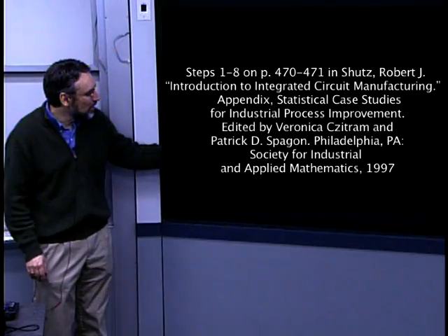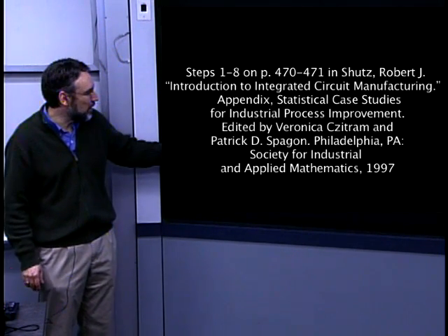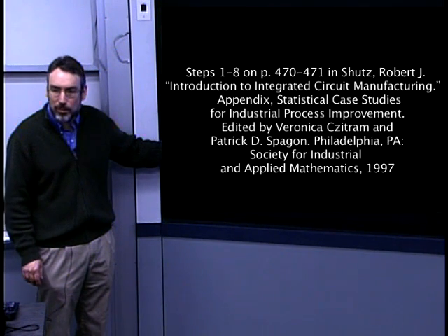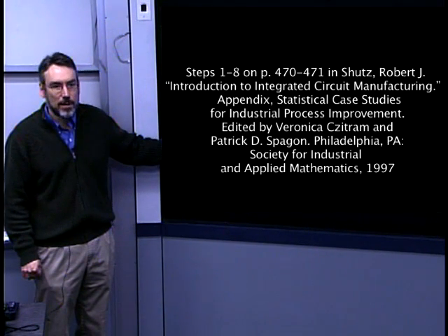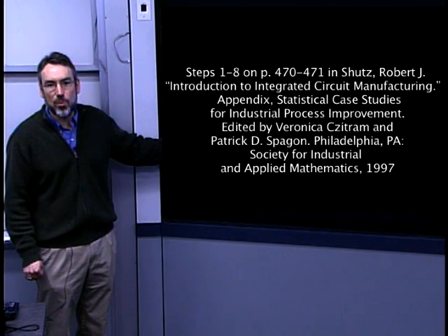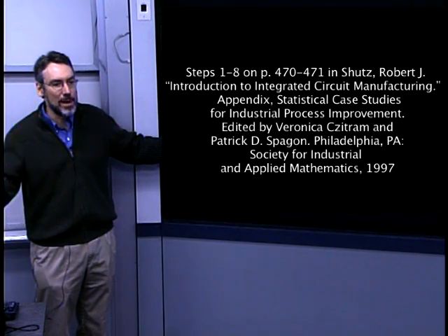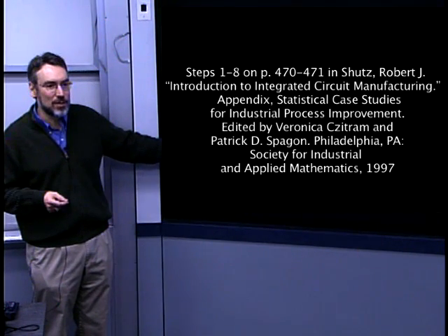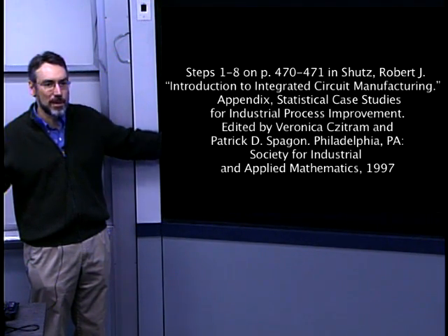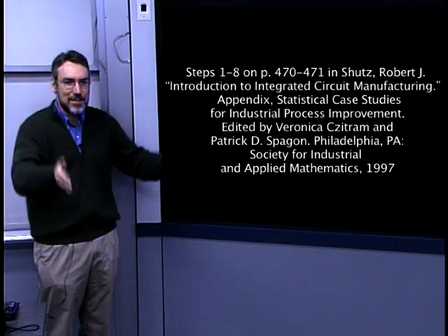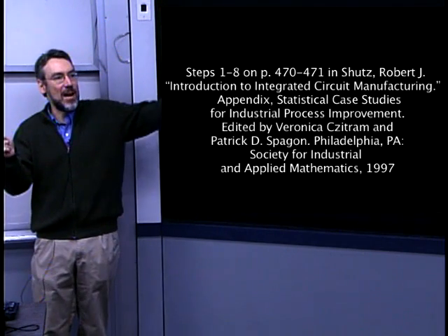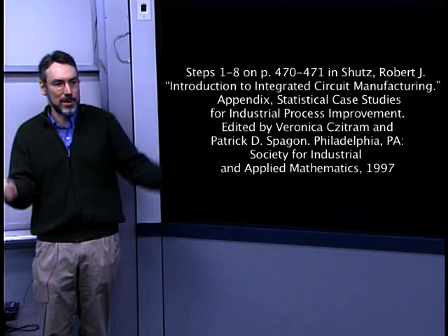At present, at least, and there are some additional reasons why one wouldn't want to do it, but at present, we don't have the observability to be able to know when we're within 100 angstroms. Second, there's no way you could be that uniform across the whole wafer. I mean, what if on one part of the wafer, instead of 5,000 angstroms, it was 5,001 angstroms? By the time I get down to etching 4,900 angstroms everywhere, that little 1 out of 5,000 controllability has been